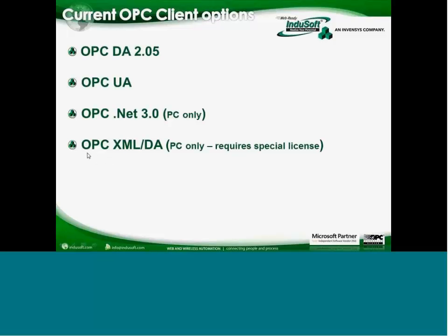And last, we have OPC XML, and our driver for this also supports DA, which you see up here at the top. This version of DA supports not only 2.05, but it also points to the 3.x specification as well. Something special about this, two things. Number one, it requires an additional license within InduSoft Web Studio, one of the rare occasions we require that. But the other thing is it allows you to multitask the communications, whereas the OPC DA 2.05 is not multitasking up here, or multi-threading, I should say.